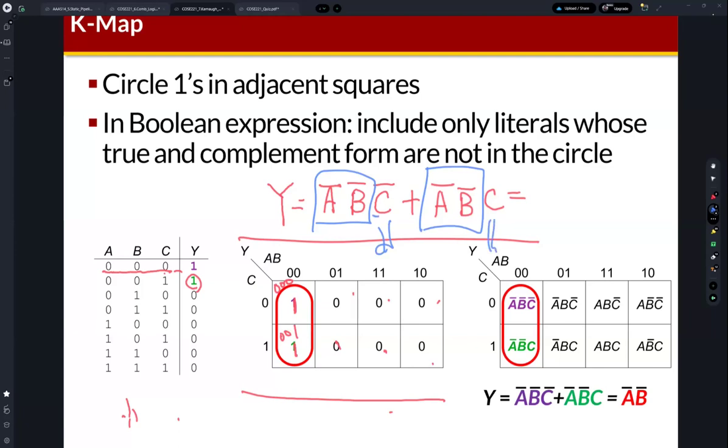So in this case, we can remove C, right? So A bar and B bar. Okay, so by doing this, we can optimize the Boolean equation. So actually, the Karnaugh map exploits this combining theorem. So how? Because in the Karnaugh map, we can find 1, 1. So this value is 1 and this value is 1. So which means that for these elements, the outputs are 1.